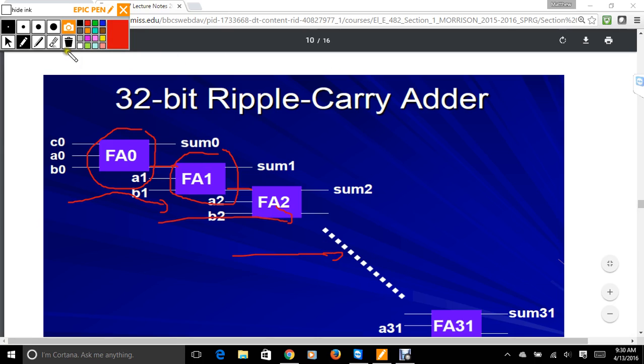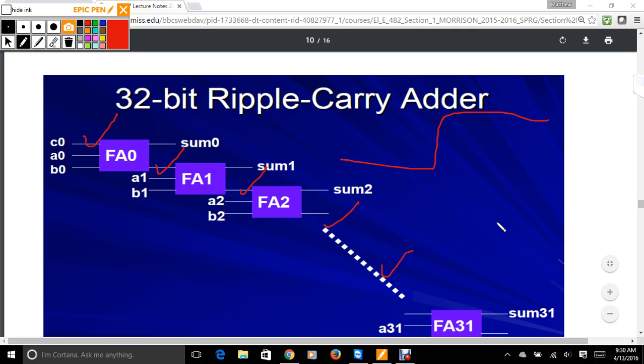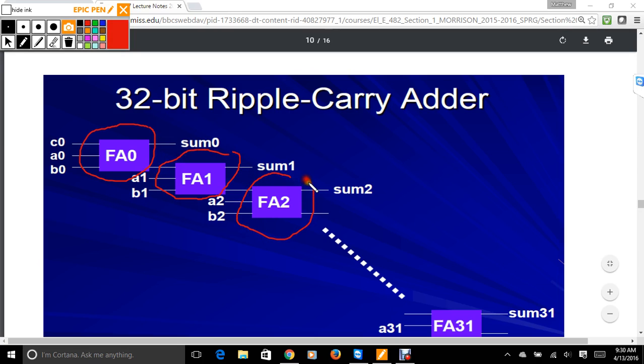Instead, you're just checking the wiring, that you're meeting the power constraints, and your noise margins. That's where this hierarchical design and the Gajski-Kuhn chart that I always present at the beginning of my classes come in. Understanding that is so important because now you're significantly cutting down on your design time.